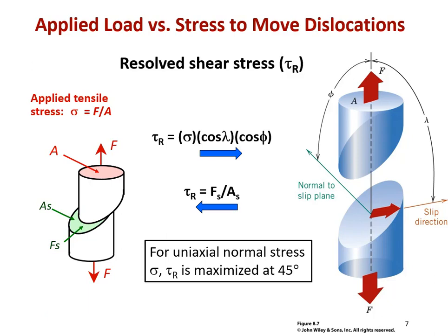So now we have a double dependence. The material is preloaded with dislocations, and if it's polycrystalline, you have those crystallographic systems also oriented randomly all over the material in every direction. The dislocations that will move first are the ones that are simultaneously oriented such that their slip planes are at 45 degrees to the applied uniaxial tensile stress and are also close packed planes and directions. So there is a bit of a hierarchy of which systems will activate first and allow dislocation movement first.